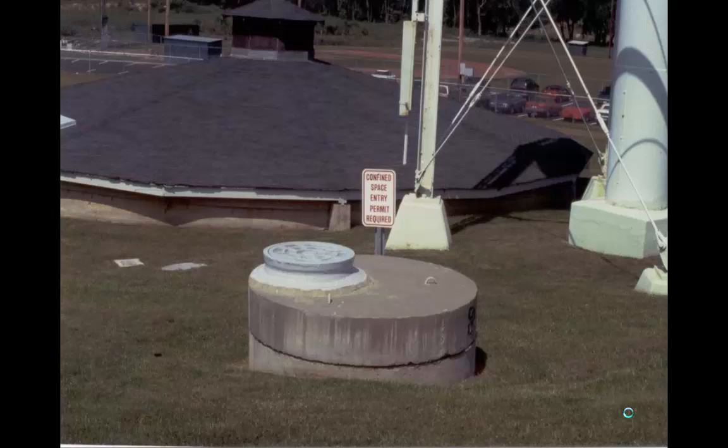But for the other areas that don't have that stamped on there, the standard also states in the confined space program you have to limit access and egress if employees are expected to work in them. In that case, a manhole is out in the general open. It does have a very big limitation on getting in, because you're not just going to walk by one of these manholes, bend over, and just flip it off. It takes a considerable amount of effort to get these manhole covers off.